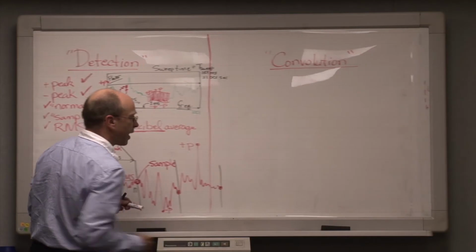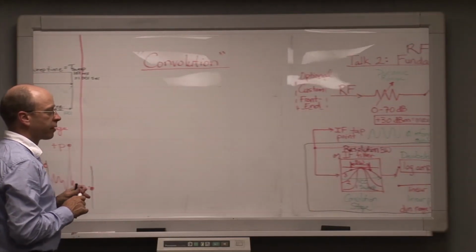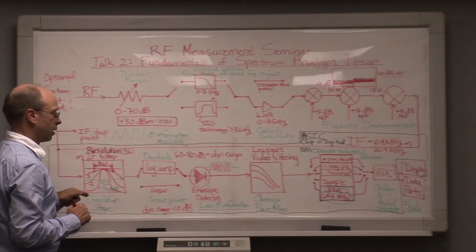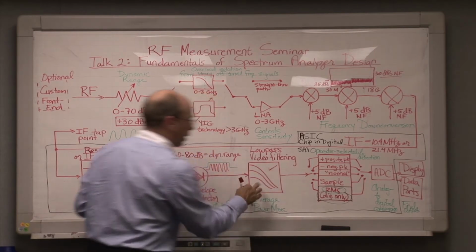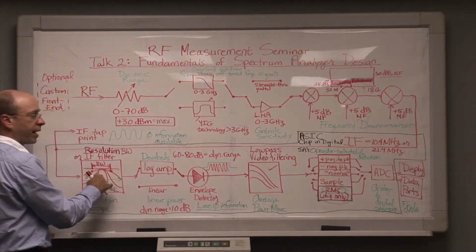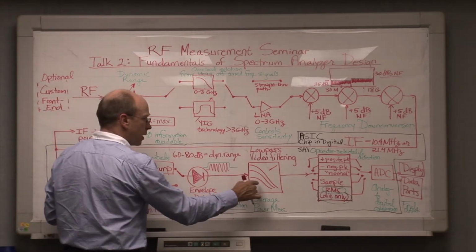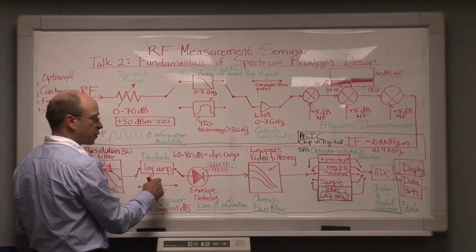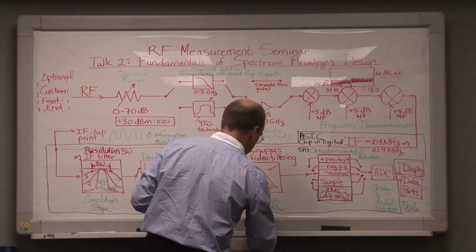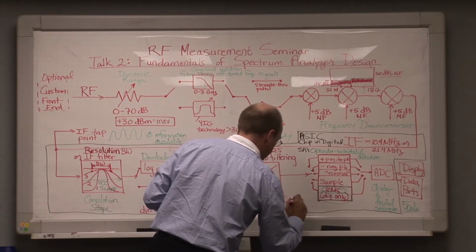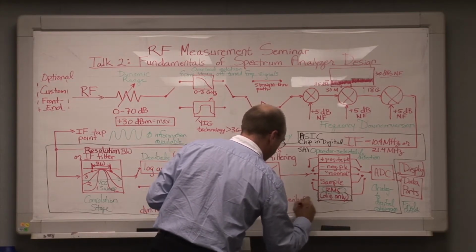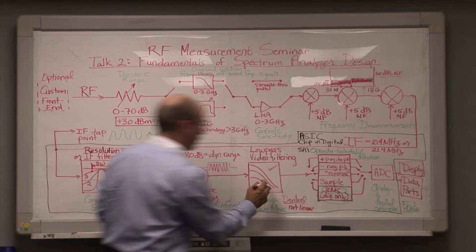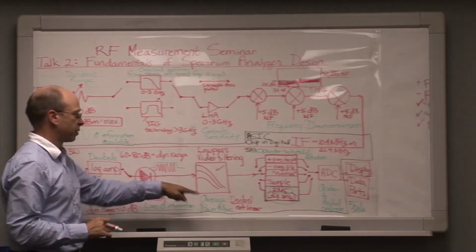One thing that I do want to point out with that said is that if you're using an analog spectrum analyzer and you want to get average power using narrow video filter widths compared to the IF filter widths, in fact, because we're working with these video filters after the log amp stage has been passed, I should make note of that we will in this case get a decibel power average, not a linear power average, if in fact we use this technique with an analog spectrum analyzer.